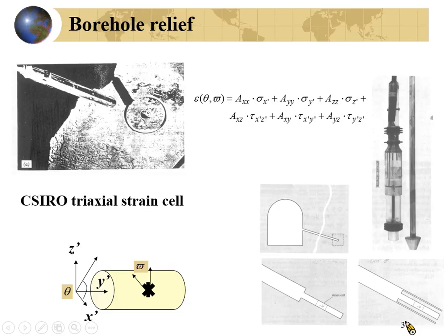Can you understand? As I showed you, when you have the strain gauge like this, if you want to determine the stress in this coordinate system, then you will have epsilon A, epsilon B, and epsilon C. And you can determine the sigma x and the sigma y and the tau xy. Epsilon x, epsilon y, and the gamma xy. You can determine this from this and this. During the calculation, you need to have the theta, right? So right now the theta will be the omega.